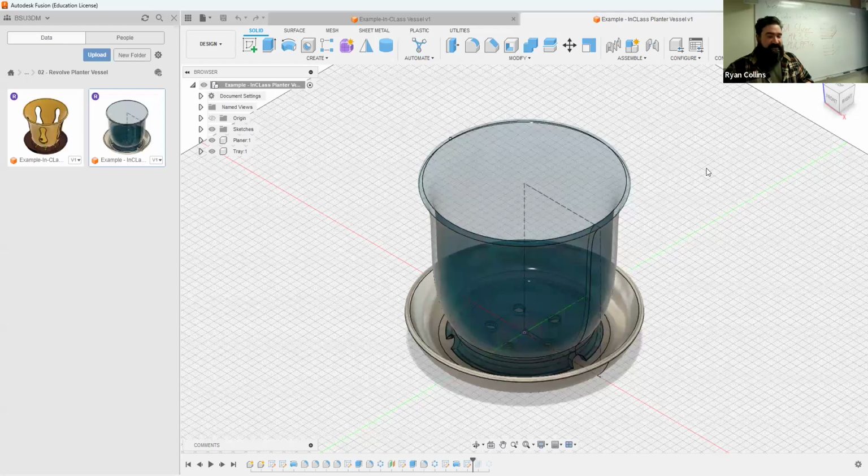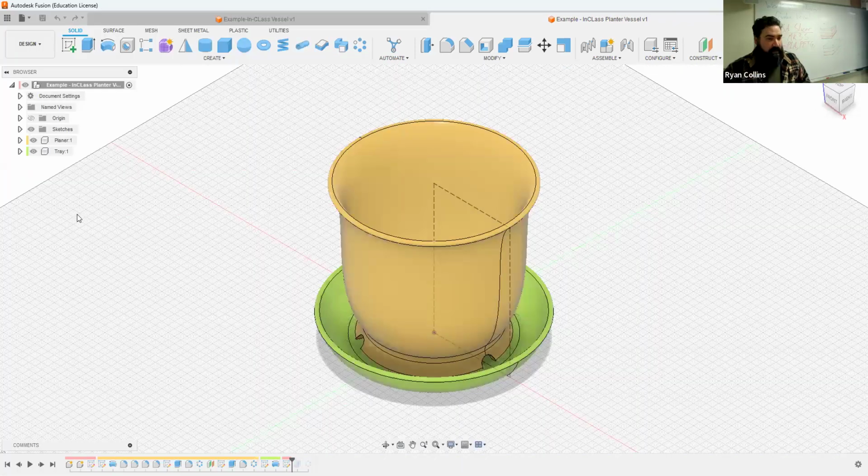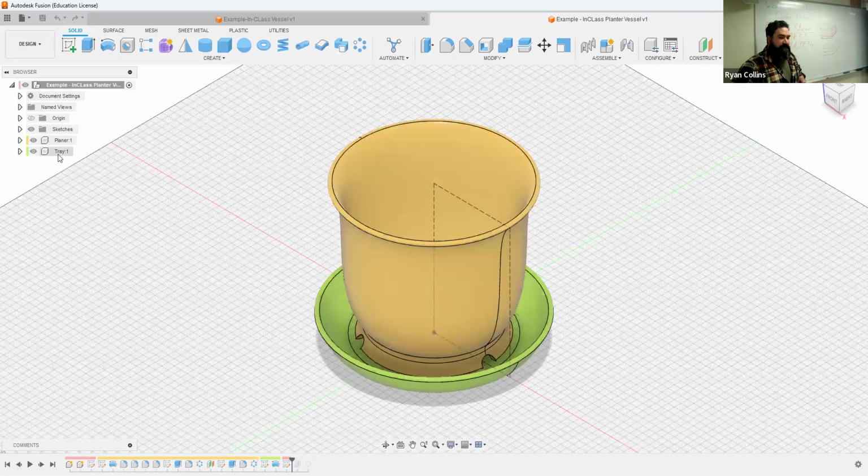I got a couple of examples. So essentially, and this is using the appearance tool here. I'll shift back to auto color here. So as example references, one of the main things is it must be on two separate components. I'll show you how to do that, a couple different methods. But each component has its own bodies and sketches. The sketch creates the body.